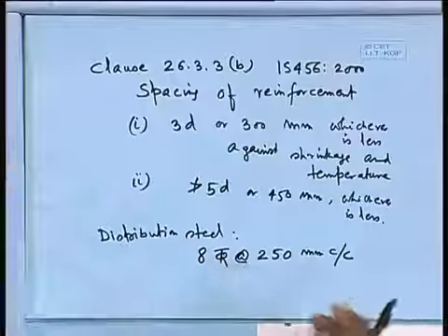Now, finally, we have to show the detailing. For reinforced concrete structures, we have to show the detailing. That means, for beams we have to provide the cross section, also one longitudinal section. In the longitudinal section you have to provide where is the curtailment of the reinforcement and how is the steel spacing, and your cross section will show a typical cross section. That means at which section you are taking along the longitudinal one. Here also for slab, we have to provide the reinforcement detailing.